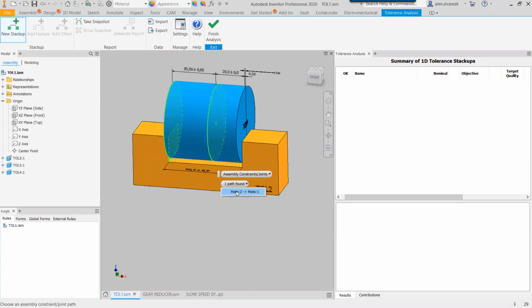Again, why are we interested in these constraints here? Because that gap, depending on what that gap is or what the tolerance for these components is, is going to affect the spacing in this entire slot. So if we have a small or tight tolerance for these, you're going to have a bigger gap. That's going to affect the overall slot, right? So we're essentially analyzing the loop between this face right here, this face, and then this face pushing up against this opposite face of the actual block, right? So that's why it's important to really understand which loop we're going to be analyzing.